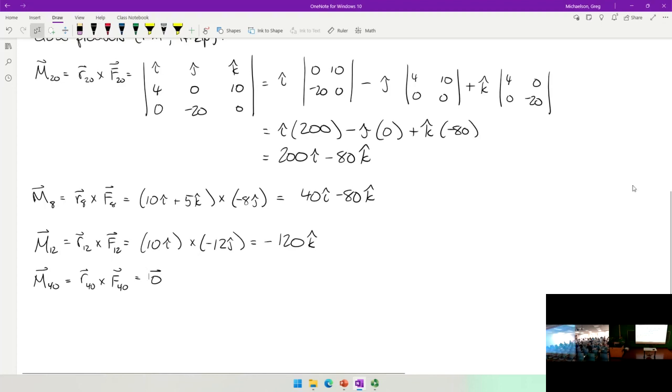So, if I wanted to replace this with an equivalent force couple, what I would do is say, okay, R, my resultant force vector, is just the sum of the individual forces. But what is that? What did we have? We had 40, 12, 8, and 20. So 12 and 8 is 20, 40. I think that's 80. Did I get that right? I think that's right. And that's in kips.